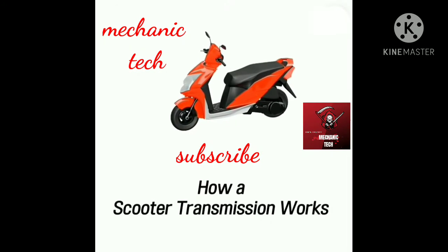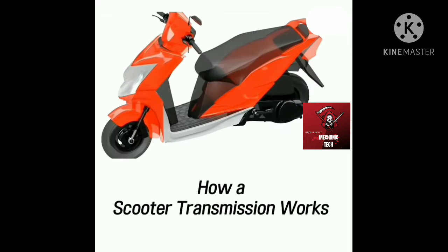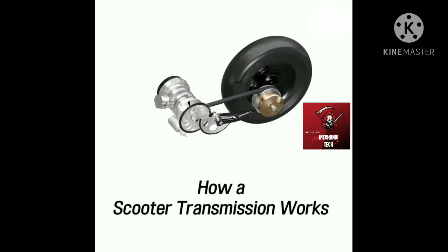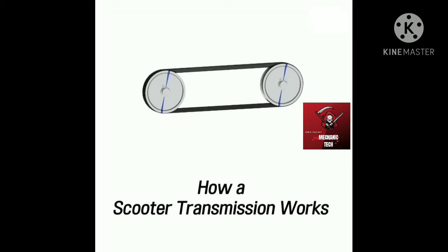One of the most common two-wheelers popular in many parts of the world. They are typically equipped with an automatic transmission system. This transmission system is known as continuously variable transmission, or CVT. The basic principle of a pulley-based CVT can be demonstrated by using this simple setup.